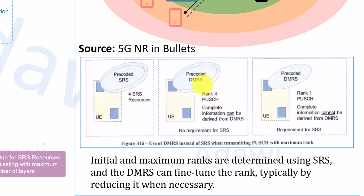You will have the DMRS all the time, as you know, associated with the PUSCH. So in this case, since the maximum rank is already being used, for uplink channel propagation the gNB can use the DMRS instead of SRS. And why will it do this? To reduce the overhead of the SRS, so it can maximize the user throughput by using the DMRS to estimate, for example, the rank and so on.